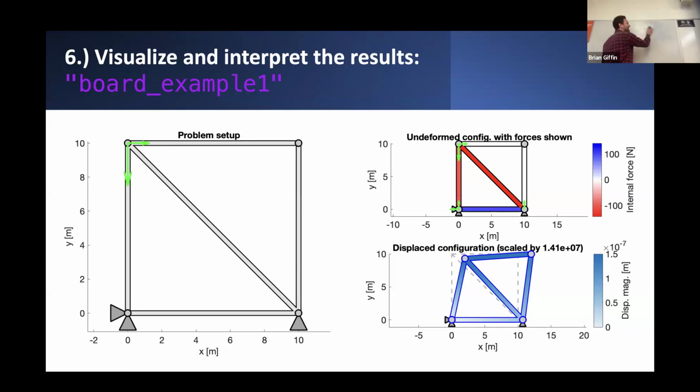Yeah. Again, it helps to go back to your classic statics and think in terms of the method of joints approach. If we know that vertical member coming into this bottom right joint is constrained here, it's going to have a reaction force pushing up. It's going to have some compressive force pushing in on this joint. There's a few different ways you could rationalize this, but the sum of forces in the x direction requires that this force pushing this joint to the right has to be balanced by some tensile force pulling the joint backwards, or to the left. So that's one way you could rationalize what those internal forces should be, recollecting how the method of joints gets applied in this context. So that's not so bad.